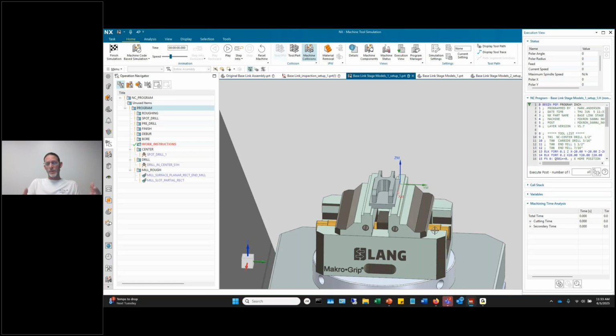So the right process would be you have your design group, your manufacturing engineering group, your CAM group, your CMM group. Everybody is talking the same information, but it's all being pushed by your design group. So if I get a part that a customer sends me in Creo and says, I need you to manufacture this, first thing I do, it doesn't matter how much ancillary data they give me, first thing I do is turn it into an NX part. Second thing I do is open their print and copy their dimensions into PMI data. That's the very first thing before it gets processed at all.